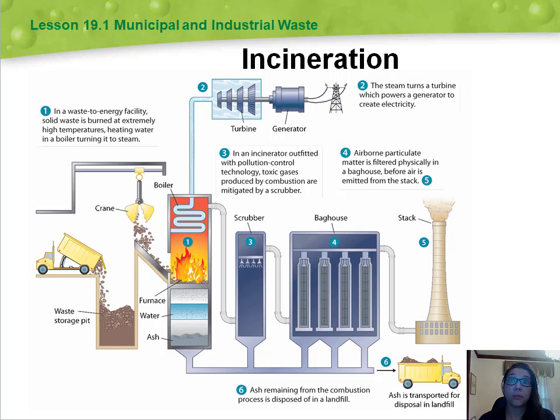They have something called scrubbers, which chemically treat the gases produced in combustion to remove hazardous components and neutralize acidic gases, such as sulfur dioxide and hydrochloric acid, turning them into water and salt. Scrubbers generally do this either by spraying liquids formulated to neutralize the gases or by passing the gas through dry lime. These scrubbers are similar to the ones used to treat smokestack emissions from coal-fired plants.